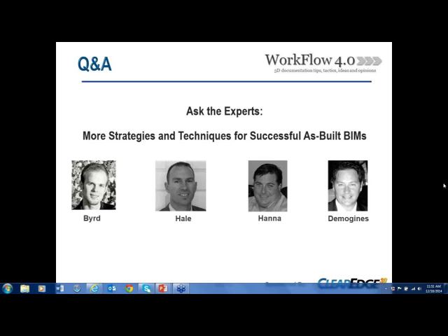Yeah, I actually use Bluebeam Review. It's basically just a PDF markup tool, but it also has a database built into it. So based upon something like a walkthrough, or if someone gives me some initial floor plans, I can set up a sequence, basically plotting points of expected scan locations. It'll count them 1, 2, 3, 4, 5. Each one is associated with a time and a cost, and then that basically just adds itself up.